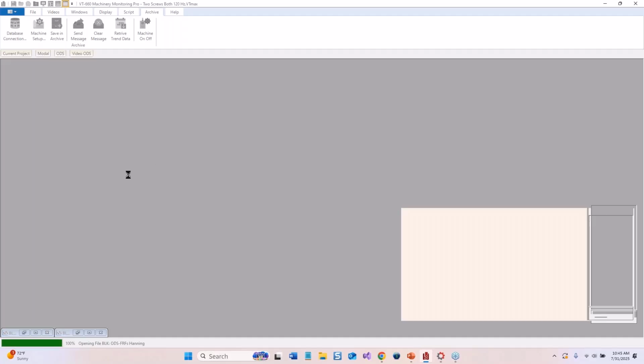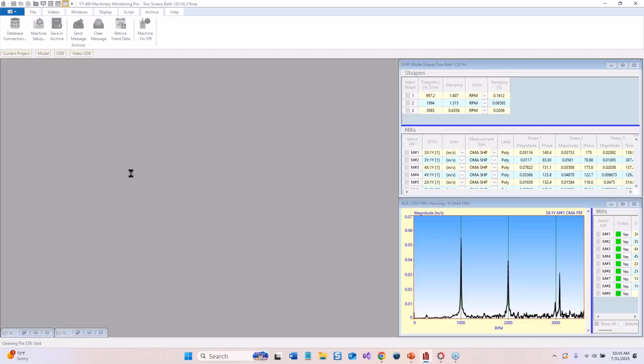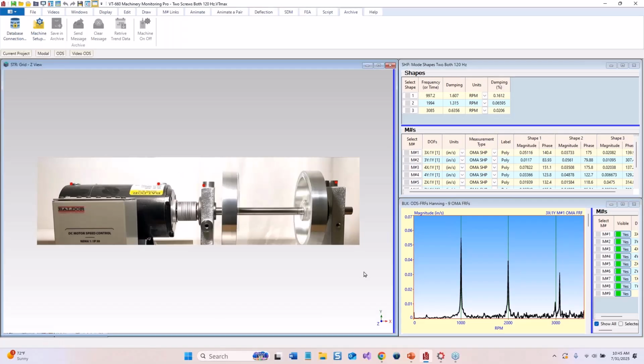So this is an example with the 2 unbalanced screws on the inboard and outboard rotor. This is going to create a lot of vibration, and we'll see in a minute what it looks like. Okay, so here it is. I've reduced the model down even further. We can go back into the wizard and do this. So I just have 4 points: 2 different points on the motor, one here on the bearing block, and then another one.